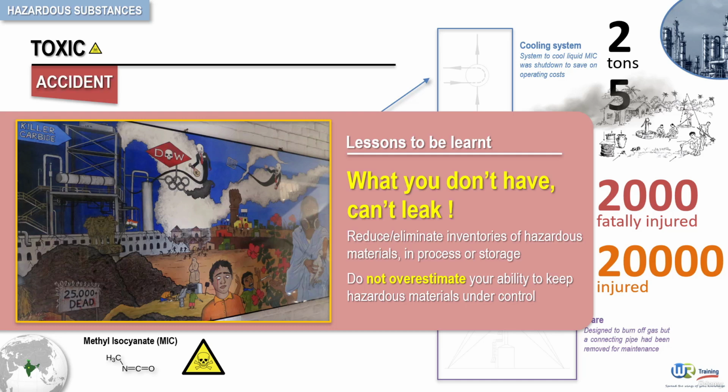Intermediate storage is usually wanted by plant managers as it makes operation easier. One section of the plant can operate when another is shut down. In addition, engineering studies on equipment availability always show that intermediate storage is needed. However, they do not allow for the fact that if intermediate storage is available, it will always be used, and